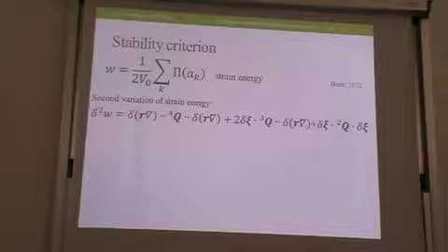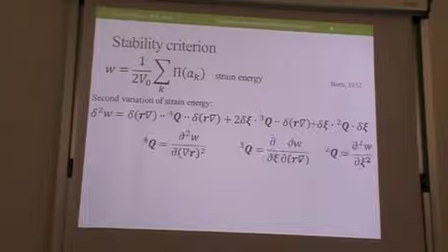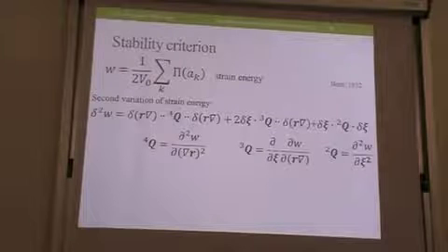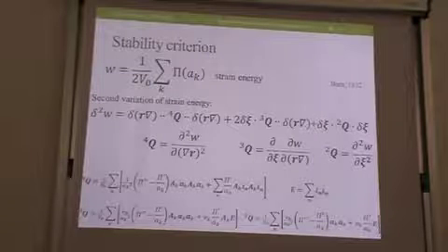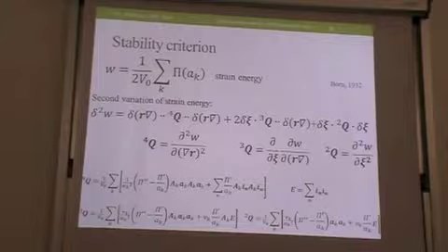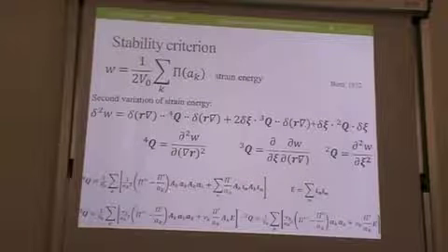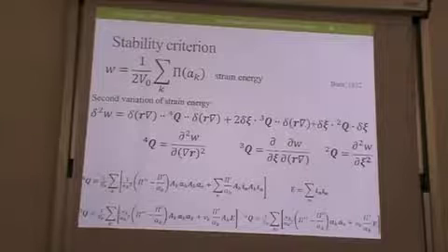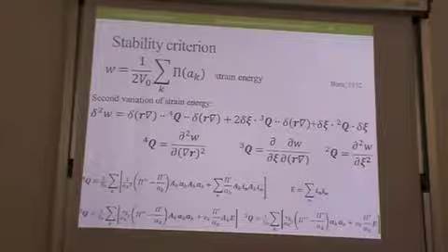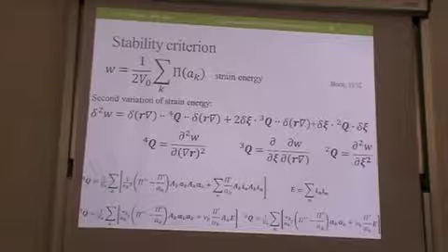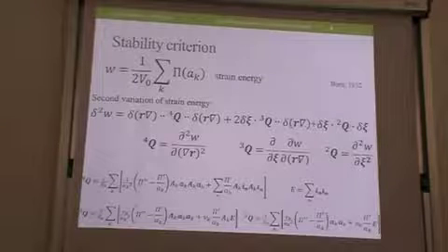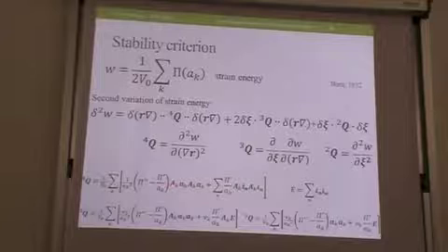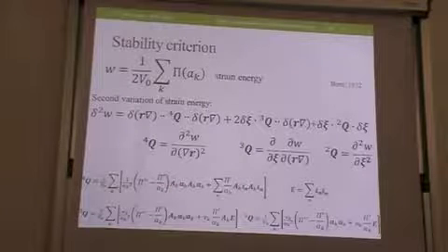Then we take the second variation of the strain energy at the equilibrium, where the coefficients are tensors of fourth, third, and second rank, just derivatives, nothing difficult. And here is what they look like in terms of current and reference configuration vectors. And all this complex stuff depends only on the geometry that was introduced in the previous slide. It just may look a bit too large. And here the tensor product is omitted. So here, and here we have the tensor product.